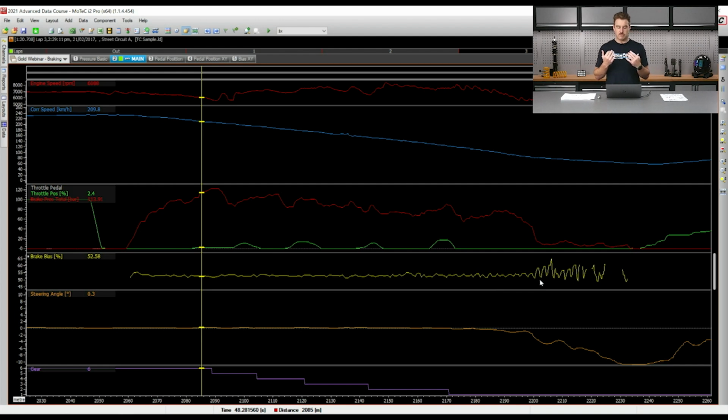That's where you get more stiction, more of any sort of hold-ups you've got in the whole brake bias setup. There are a lot of different joints in the pedal box. What I mean by that is there's a whole lot of different bushings and bearings. As you get lighter and lighter pressure, the friction in each one of those different systems tends to hold up one side of the master cylinder more than the other.